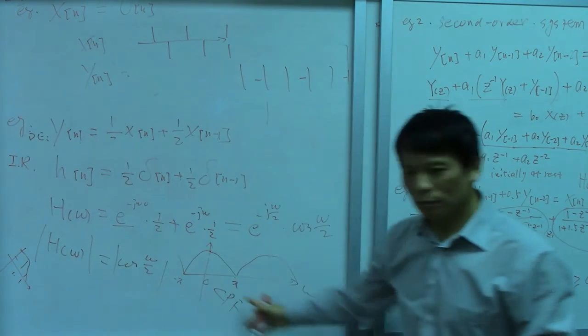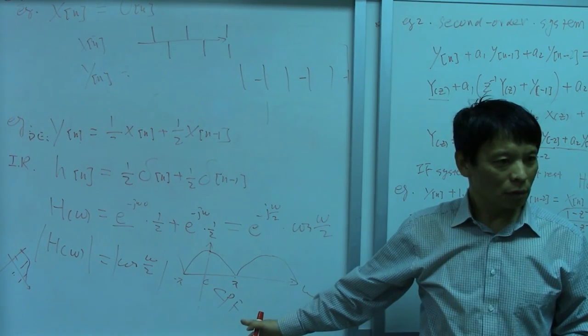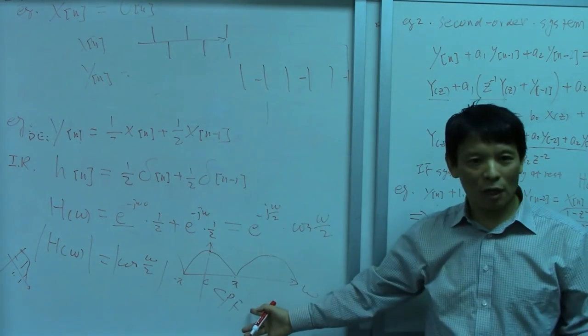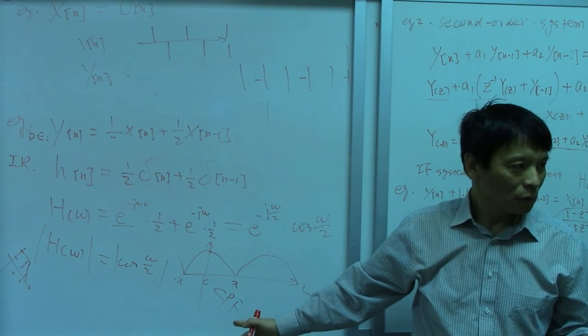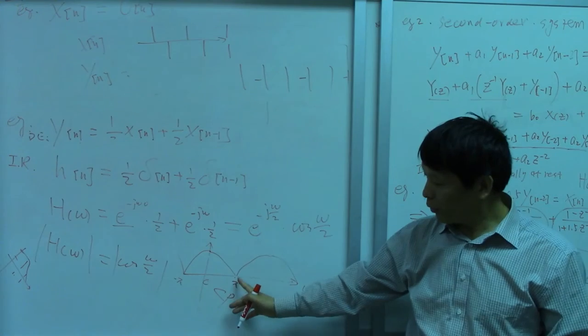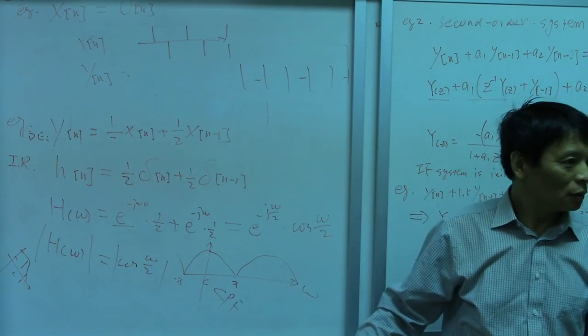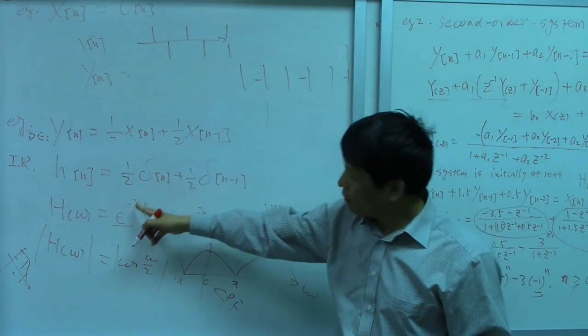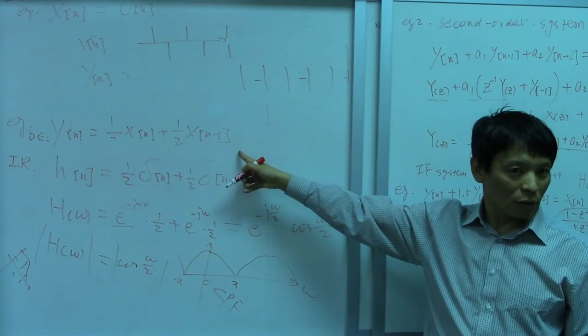First, from here, what is the output? Don't look at that signal. Just tell me what the output is from the frequency response. 0, right? Because this is very high frequency, so the gain equals 0. So 0 times the input must be equal to 0. Now verify by yourself. This is the system. Equal to 0 or not?